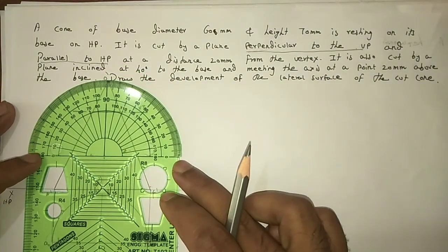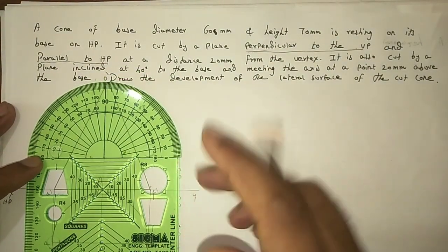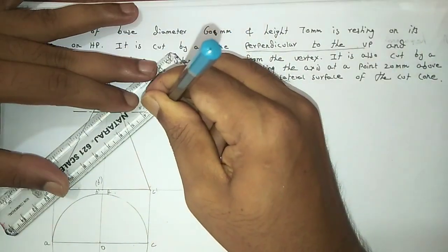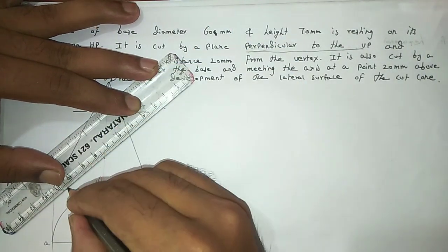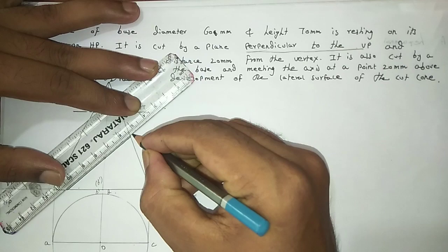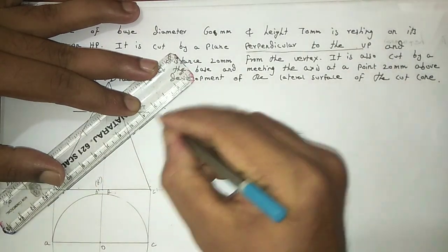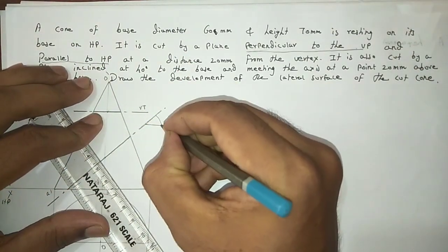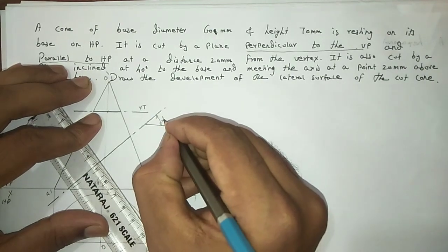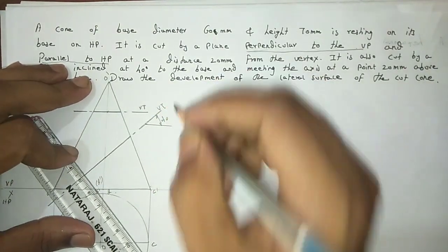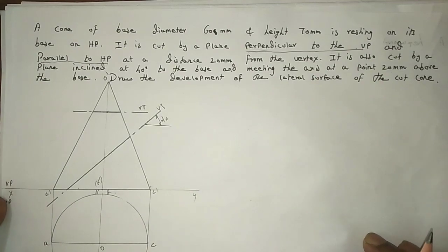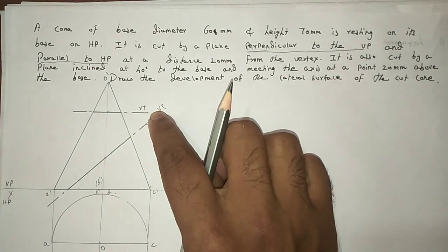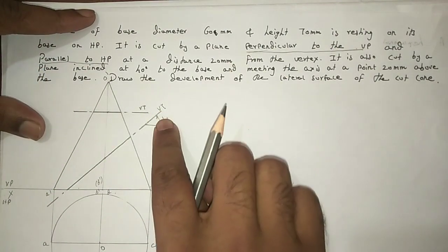So first you place the protractor like this and take the angle 40 degree. And now draw the cutting plane. Inside the object, draw a darker line, and like this we draw. And here we need to mention the angle. This angle is 40 degree, and the name of this section plane line is VT. And now here we can see this cone is cut by two section planes.